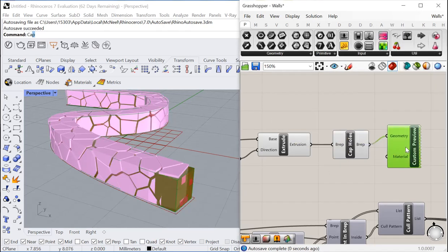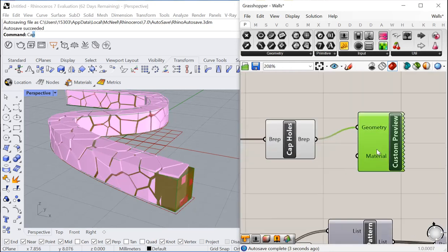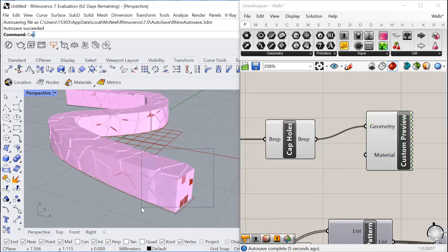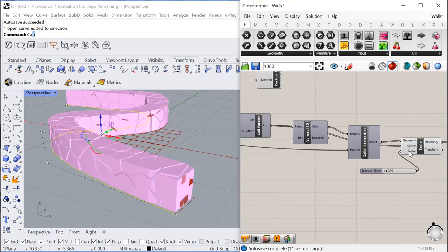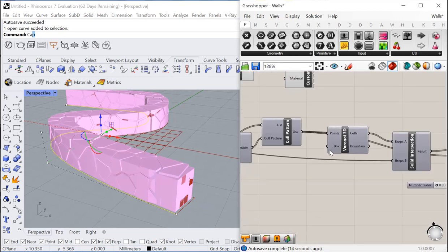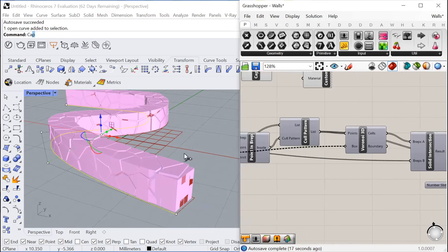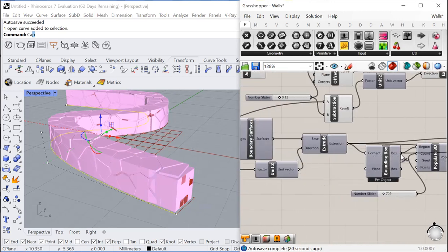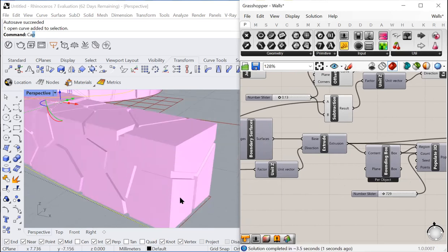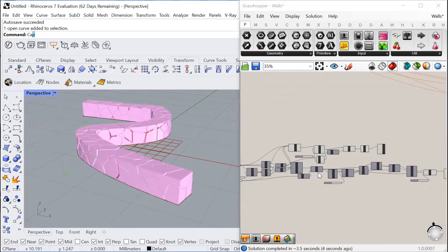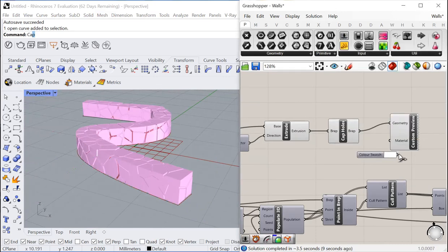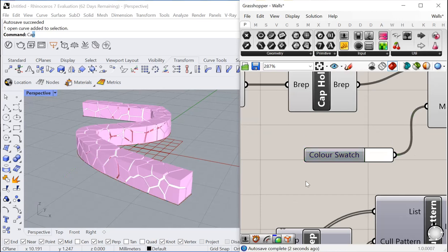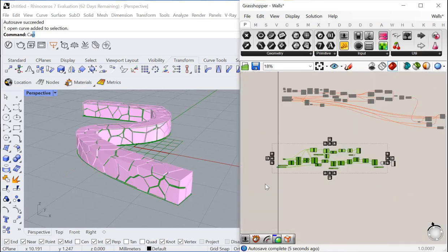and this will be the infill. You may be noticing that there is an issue here, and it is evident right here. And one way we can fix that is by taking our Voronoi 3D and making sure that we plug in the correct box, because we forgot that step. So we'll use this bounding box and make sure that we're not cutting off any of this wall. And now you can see my program updated, and if I add some colors, it will begin to look a little more realistic. Great. This is all about creating stone walls in Grasshopper.